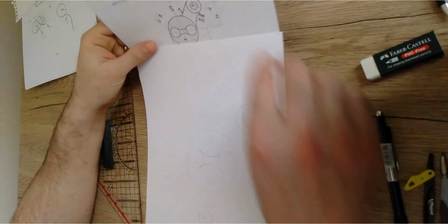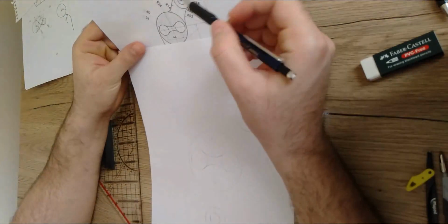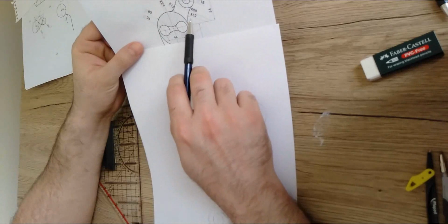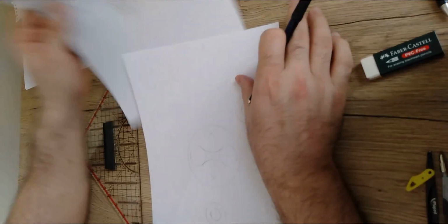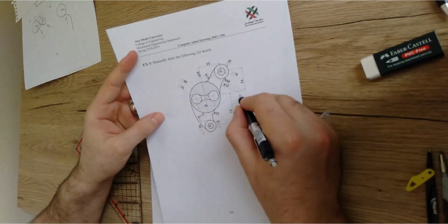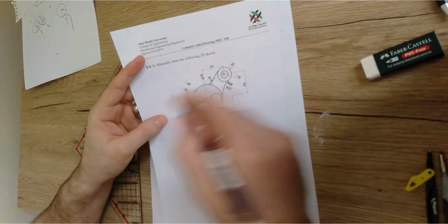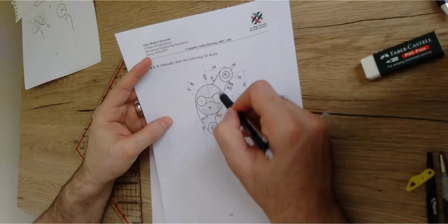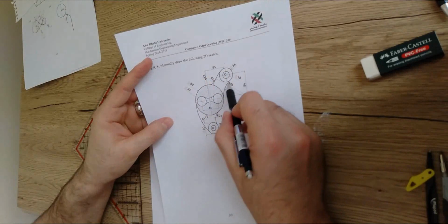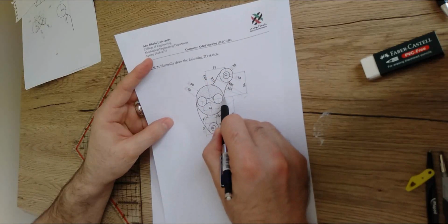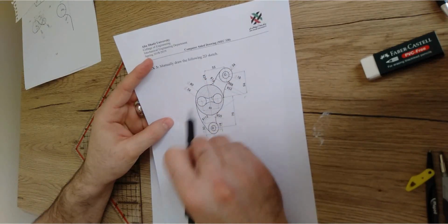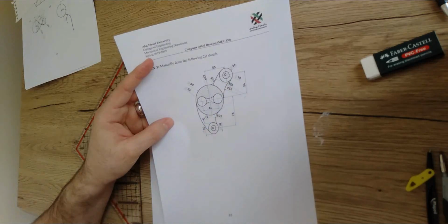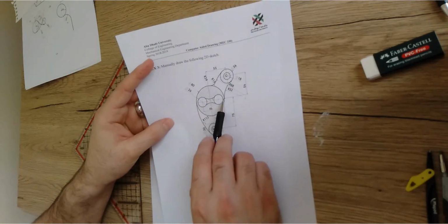Let us start with this curve here on the top. You can start with either one, it's up to you. This one has a radius of 52. Do you see it? And its center point should somehow be located in this region, for example. Let us assume that it is here. Then for this curve, you have to locate the tangent points. This curve is tangent to this big circle at this point, and it is tangent to this small circle at this point, right? So this is one tangent point, this is another tangent point.